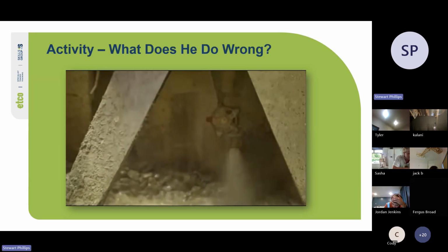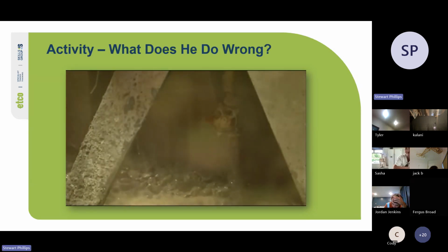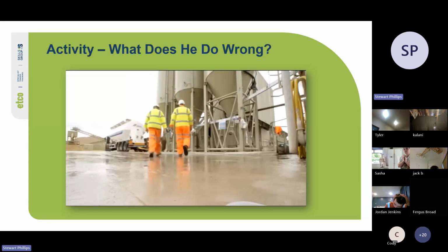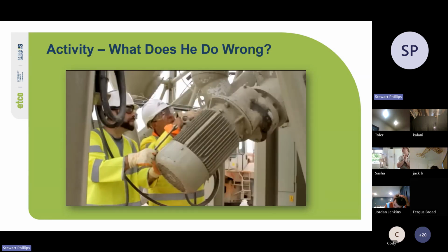In this case, it's water. They drain all the water out of the system. Oh, sorry, the water that collected in the bottom of the compressor also comes out. If any of you have drained an air compressor before, you know a lot of water condenses inside the machine, so you've got to drain it regularly to make sure that gets gotten rid of. So now it's safe to work on the equipment because the pressurized air is gone.